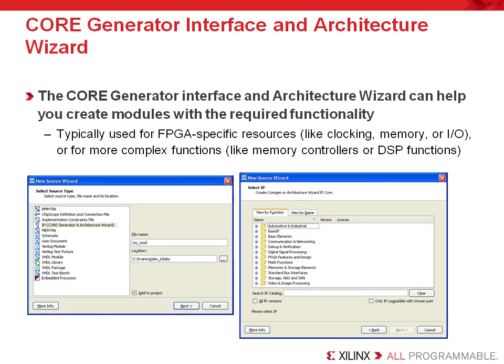The core generator and architecture wizard make larger optimized components easily available. While some cores have a charge associated with them, most do not have a charge. The cores range from simple components to large, highly complex IP. The architecture wizard is used most commonly to customize DCM and PLL components that you may use in your FPGA.